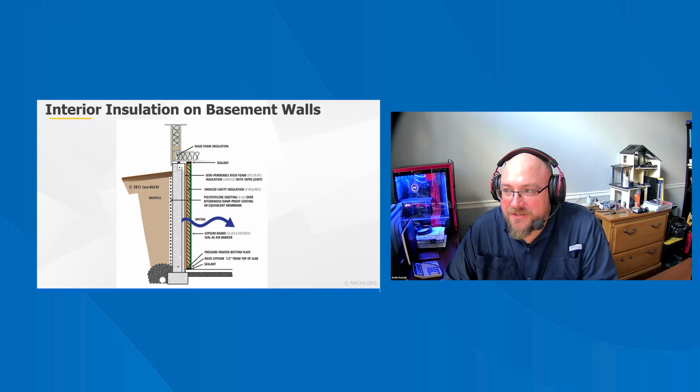Foam is a fire hazard. Semi-permeable rigid foam insulation and spray foam insulation on the inside of a basement foundation wall is often found during an inspection of a full basement foundation of a house. Its use could be a good strategy for a moisture-resistant finished basement. However, fire and smoke characteristics of this type of insulation require that it be covered with a fire-resistant layer, such as gypsum wallboard. Sometimes this requirement works fine when the basement is being finished.